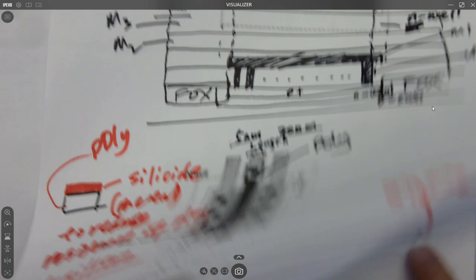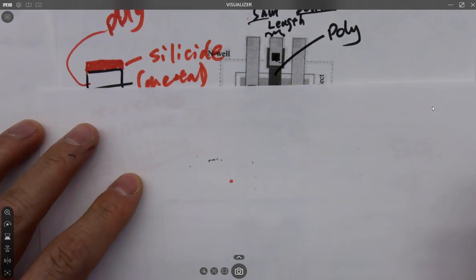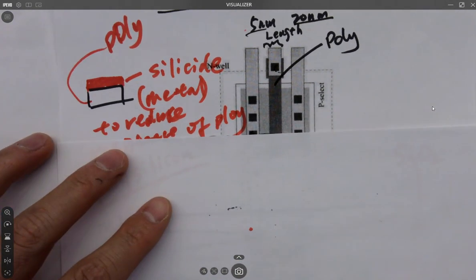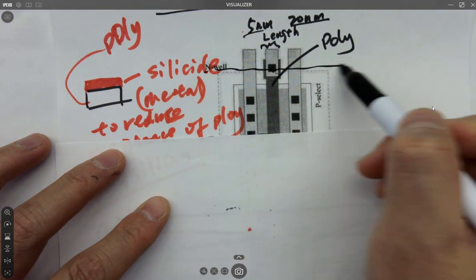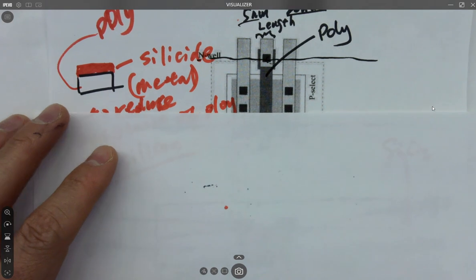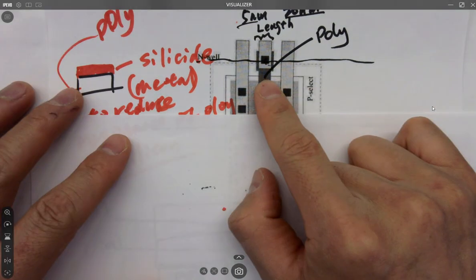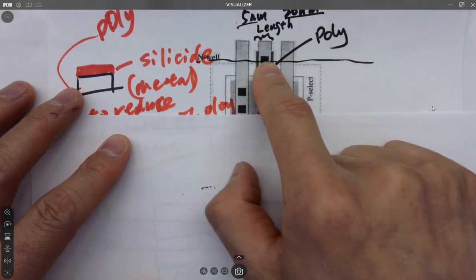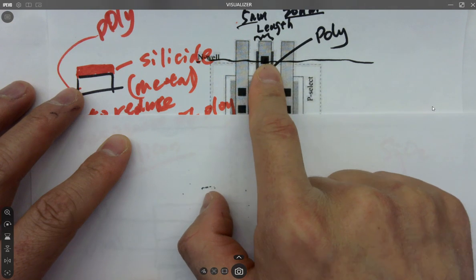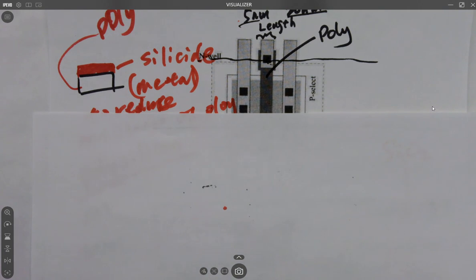Let's draw the layer for this guy here. If I draw a wire here, what's going to happen? Think about it. Take 1 minute to draw it. What is this guy? Poly. What is this guy? Metal 1. What is this guy? Via. It's the first time we draw a metal 1 to poly. See how that works. Take 1 minute to do it.